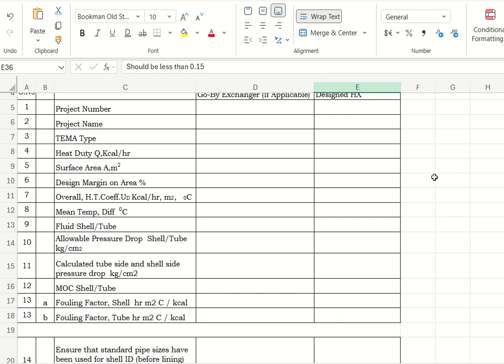I can see lots of posts on heat exchangers, so I thought of quickly sharing some of the checklist while designing heat exchangers. Be careful that when you design internal heat exchangers, get it validated with the vendor who is supplying the heat exchangers, because they have their own proprietary software which they use for their design and optimizing their design, so that in future and during operations there is no problem with the heat exchangers. So all the internal design needs to be revalidated with the heat exchanger vendors.